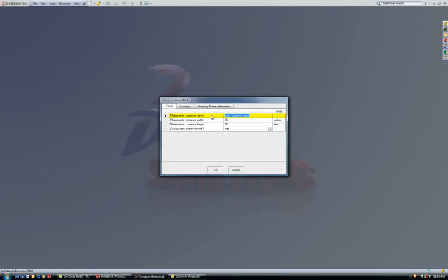So I'll go ahead and start by entering my name for the customer name. Conveyor width, let's just go ahead and up that to 40 inches wide. I need this to go 14 feet long, and I'll decide that yes, I do want a user console. Now the conveyor specifications, let's just say that I'm going to leave the belt speed at 200 feet per minute. The motor speed will stay at 800 RPM, but I want to change the sprocket diameter to maybe 10 inches, and I want this to be offset from the frame by about 14 inches.